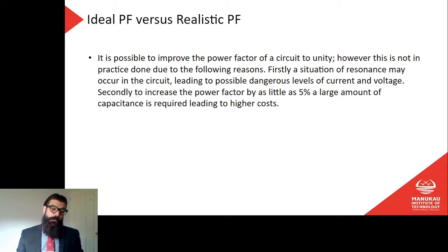If you look at the example on the previous module or previous video, you'll see that as that power factor approaches unity, the voltage on the capacitor and the inductor gets really, really high, much higher than the supply voltage. So that's an issue.